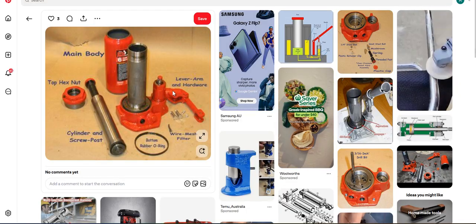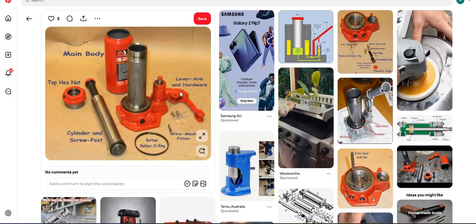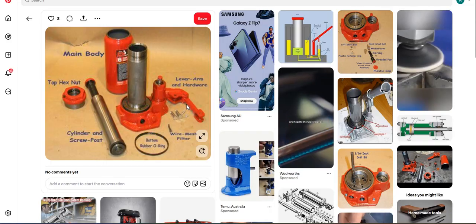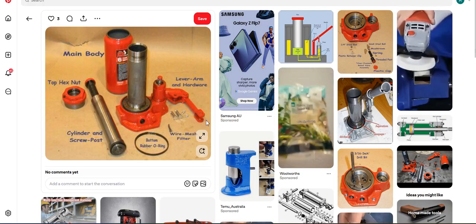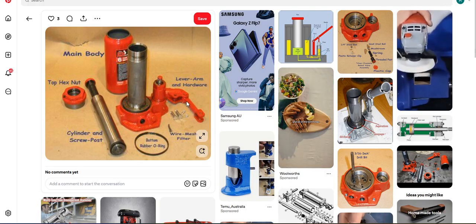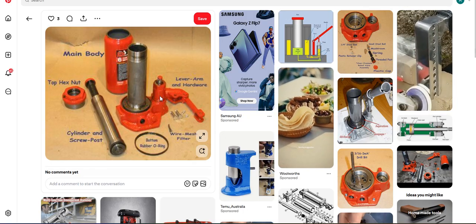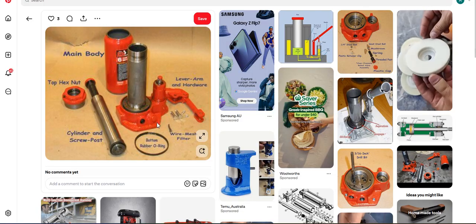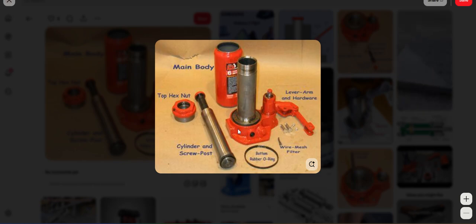This part, usually, is going to be done by the plate forming process. Then it's going to be pinned with the other one, which once again will be done from the plate forming process. This is a cylinder, and these two parts are going to be welded together. The base is done by the casting process. You can tell from the properties of the shape.